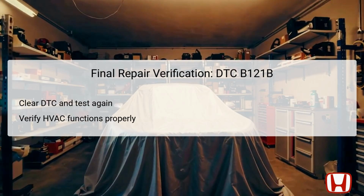After all necessary repairs have been completed, it is vital to verify that the issues related to DTC B121B have been successfully resolved. Begin this process by utilizing a diagnostic tool to clear the stored DTCs from the climate control unit. Once cleared, conduct a series of system tests to ensure everything operates normally.